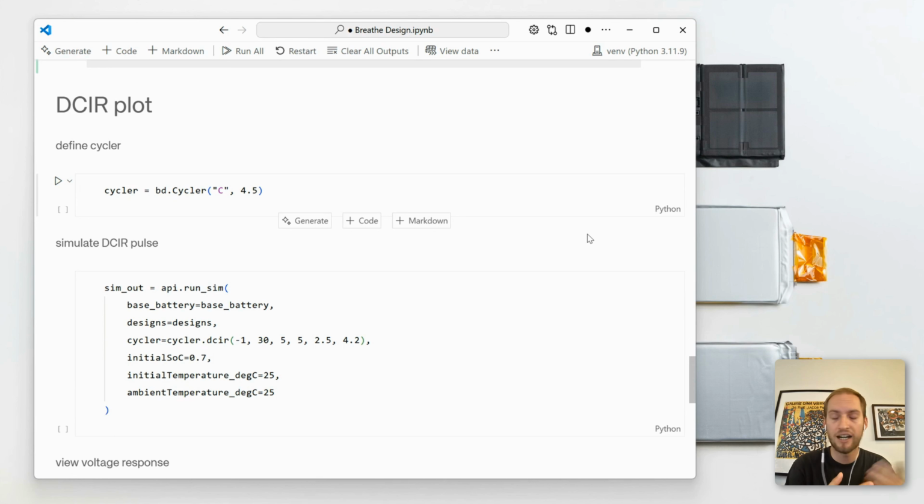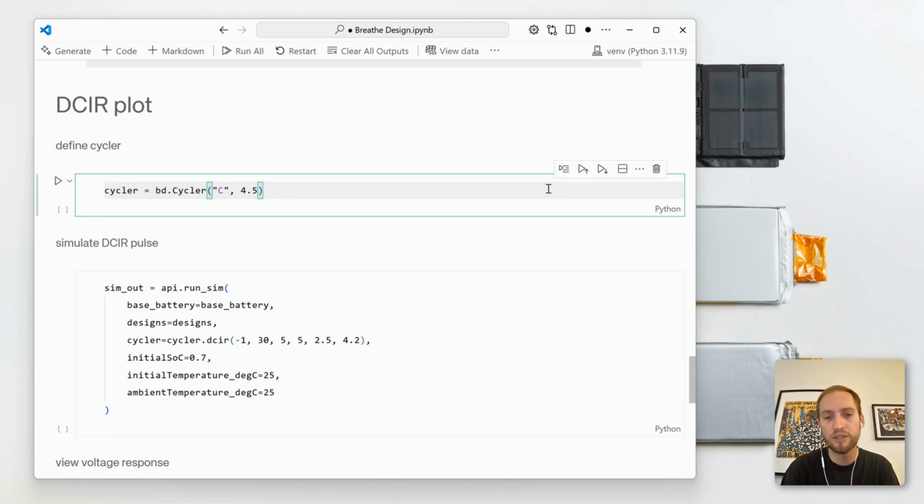Because I have high resistance, under my high load I'm going to hit my voltage limit sooner, and I'll have a cutoff there. So being able to do these dynamic simulations is really helpful to understand impacts on thermal management systems if the temperature increase goes up, and what the anode potential during fast charge might be if my resistance is changing and that runtime is changing.